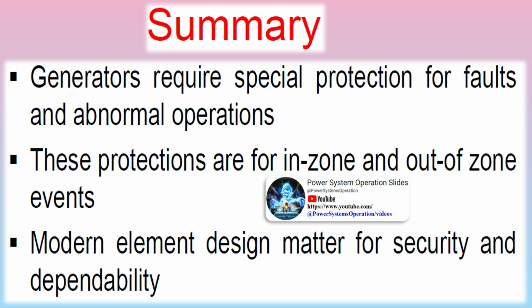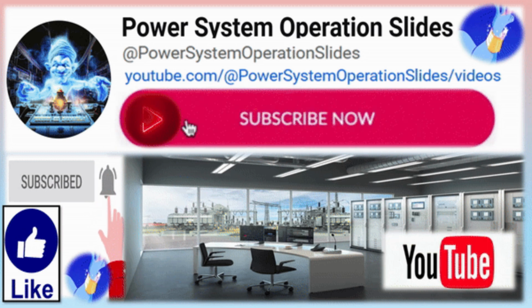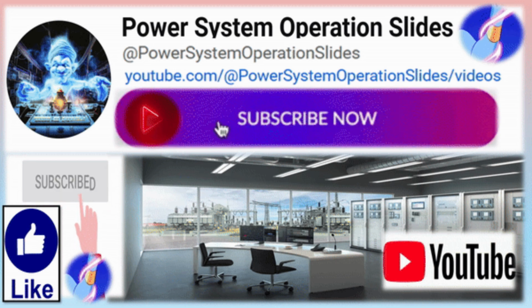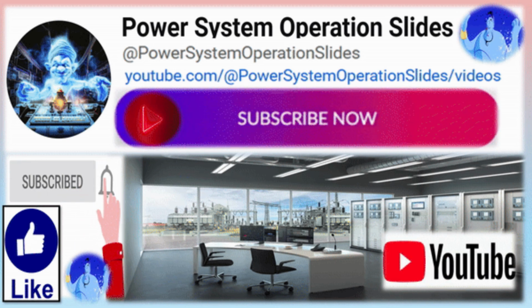Improved sensitivity: loss of field, 100% stator ground fault, reverse power, negative sequence, overexcitation. Improved security: directionally supervised ground differential protection, distance element enhancements, load encroachment blinding, power swing blocking for stable swings, new protections.